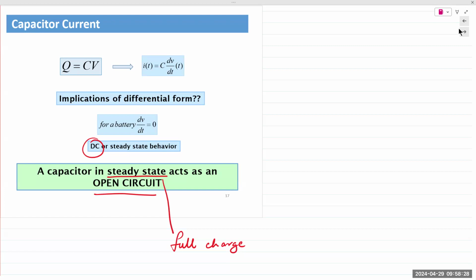Similar to an inductor, the capacitor's stored energy will oppose any change in the applied input voltage. The faster it changes, the more current actually flows through the circuit. Remember, when a constant voltage is applied, the capacitor reaches full charge and acts like an open circuit.